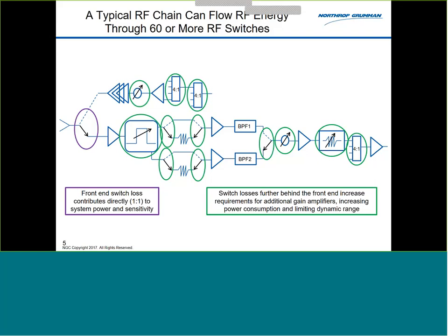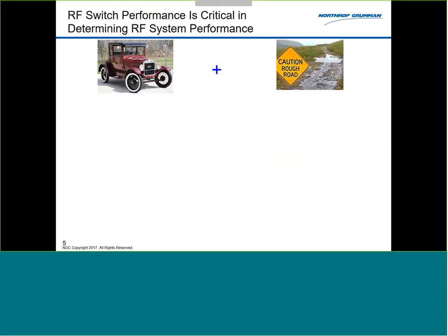And that would depend on the kind of duty cycle that you might have on that particular system and what kind of frequency. So millisecond range is often the case, not necessarily. These aren't switches necessarily that have to move fast between state 1 and state 2, but they do need to make sure that the energy that passes through them, that they're not distorting it at all, that they're not adding any loss at all. That would be essentially the goal for all those. So it's directing the RF energy from point A to point B.